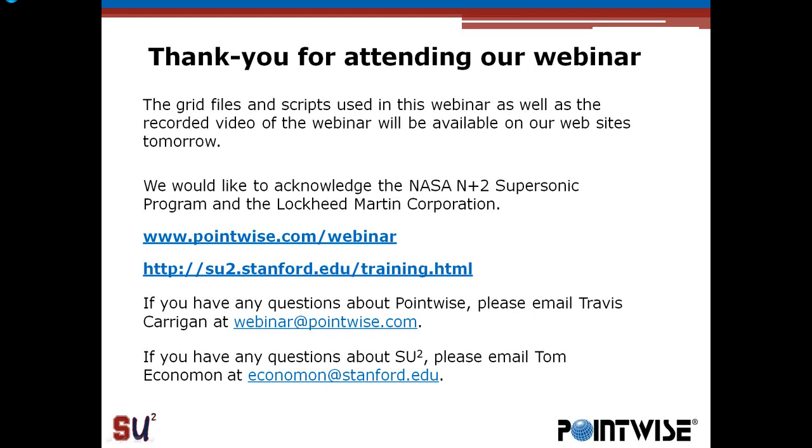So these are the conditions you'll find in the config file. Again, we invite you to pop that open. I didn't have time to go through that today. But this is the typical case that they propose on the website for the low boom. So I think it's Mach 1.6 and alpha 2.1. So you can go ahead and check that out. And yes, we do have the capability to do angle of attack changes. Mostly we do this by putting an FFD box around the entire aircraft and letting it deform the whole body, so move the whole body to change the angle relative to the free stream. So we've done this in the past, yes.